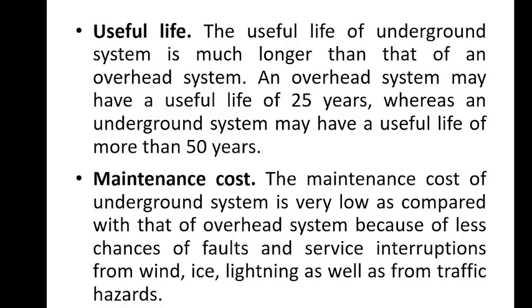This slide highlights the comparison between the overhead and underground systems in terms of useful life and maintenance cost. Underground distribution systems generally have a much longer service life, often exceeding 50 years, because the cables are protected from environmental factors such as weather, pollution, and mechanical damage.